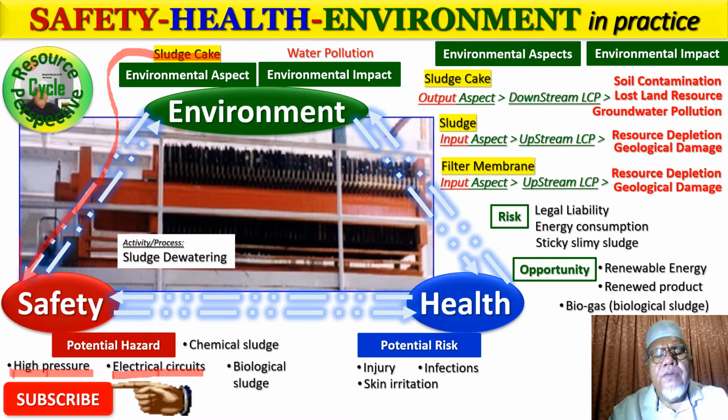Also of interest to the environment is the fact that the sludge that enters the filter press, and the sludge cake that is being produced after the press, most of it is chemical based. Remember, heavy metals, you've got inorganics, perhaps cadmium, chromium, mercury, nickel, zinc, tin, etc. in the sludge, which has been flocculated, coagulated from the coagulation process.